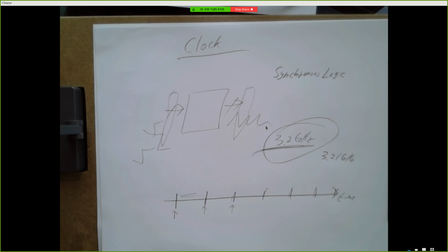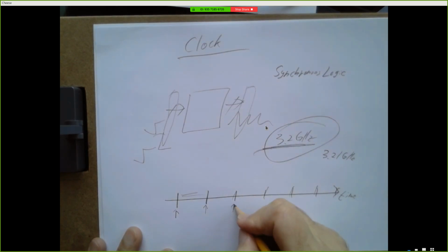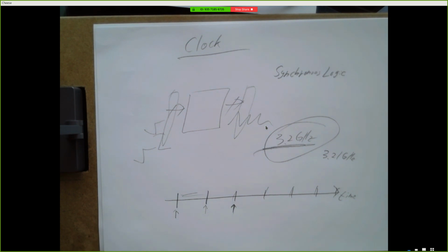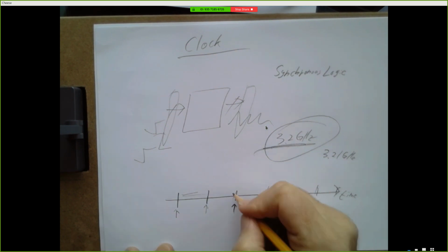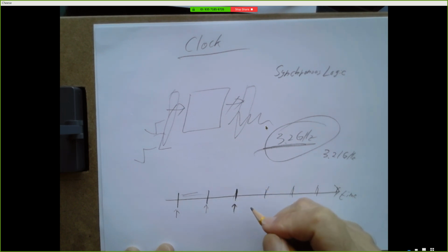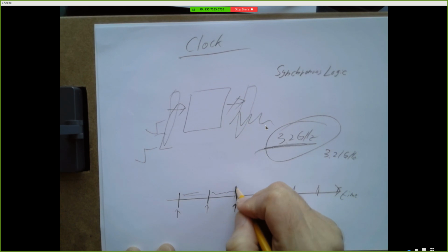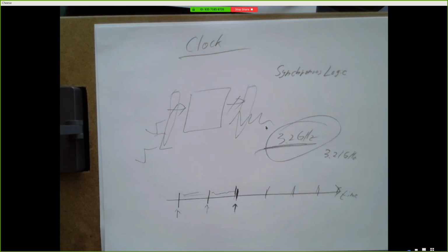That's 1/3 of a percent faster. Well, when you get a system with a 3.2 gigahertz clock, so these things are coming out 3.2 billion times a second, it's a really good bet that things are stable pretty far before this clock tick. It would be a dangerous design to say, I'm going to let changes happen right up to here, and then everything's going to be stable.